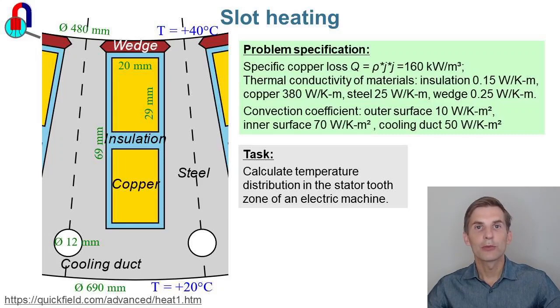Well, I'm going to simulate the heat transfer problem. And in heat transfer problem, you should specify the loss density, which is watts divided by the meter cubed. You can readily calculate this value from the current density and the resistivity of the material.